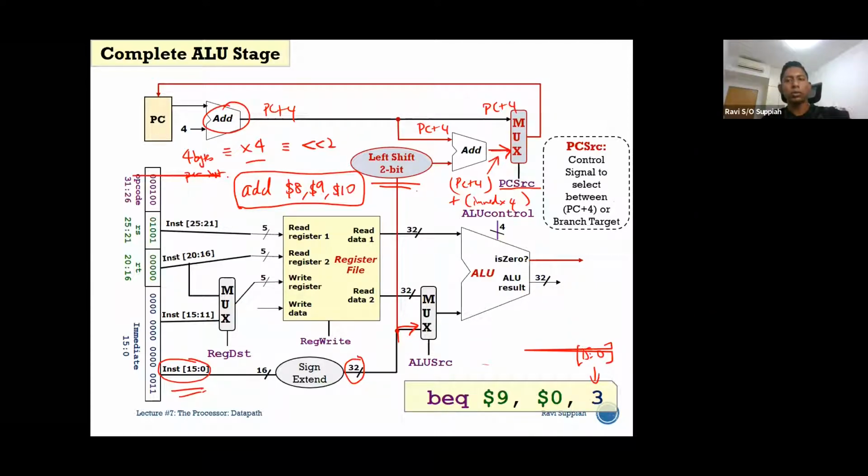All right, so there is no additional delay, because later on when we look at the timing analysis in the tutorial, you will see that operations like the register file and the ALU are going to take much longer compared to operations like the add, the left shift, sign extension, and so on. Whatever the case, all these smaller blocks of hardware are going to be much faster than these bigger blocks of hardware. So we are not going to add any delay. We are just making use of the current available time to prepare the data as much as we can.